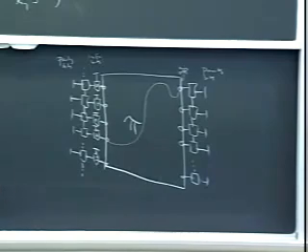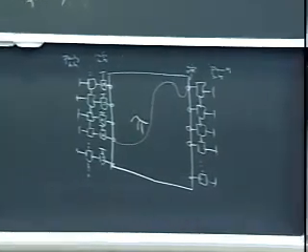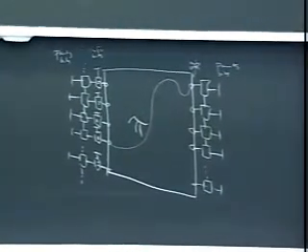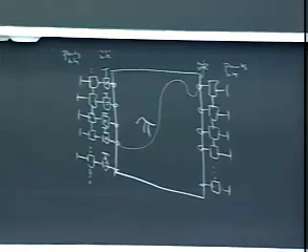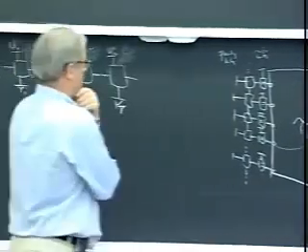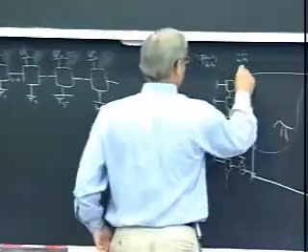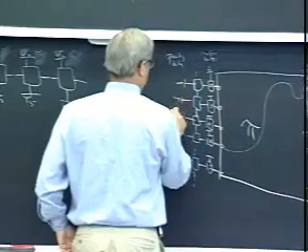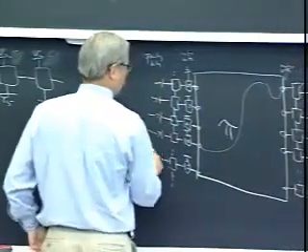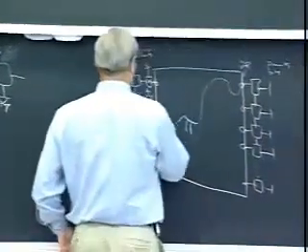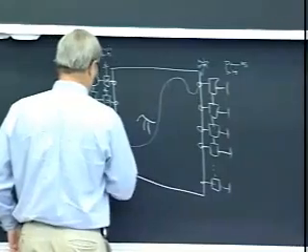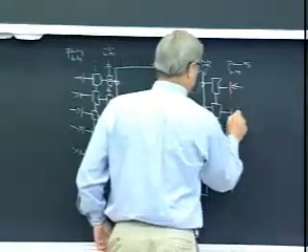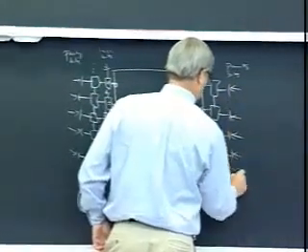All right, so how would we apply the sum product algorithm to this code? What would our decoding schedule be? In this case, when we observe the channel, we get messages in all these places. So we get intrinsic information coming in for all the external symbols.